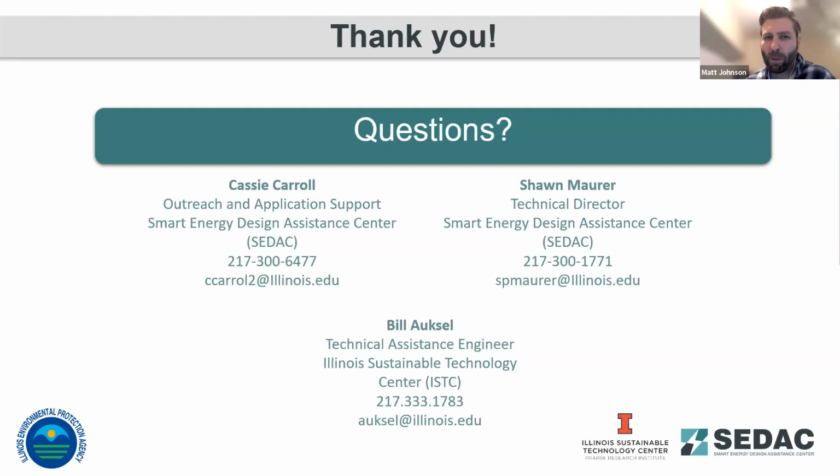So you're talking about like a wastewater lift station. There's obviously other benefits of using the VFD. You can use it for actually cleaning out the lift station. A lot of times you'll have floating solids that won't ever reach the pump inlet, but you can adjust your water level and pump down so you're kind of sucking off debris on the surface. Pumping normally at reduced speeds, you're not getting that scouring rate in your force main. The VFD allows you to get to that higher velocity to clean out your force main to the plant.